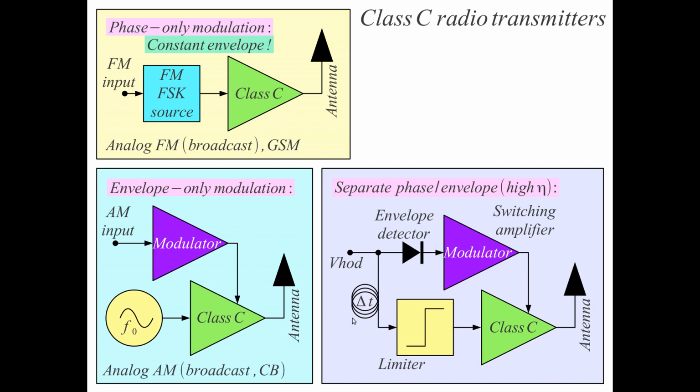We have to add a delay line here, maybe also a narrow band delay line like a bandpass filter, which also adds group delay. So for high efficiency, this is also an idea how to build amplifiers, though this is very difficult, especially it's very difficult to equalize the delay in the envelope section and in the phase section of such an amplifier. But this is an idea how to build high efficiency amplifiers.